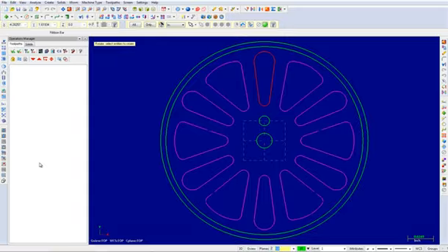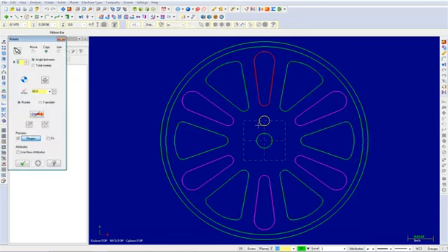Your part will appear as shown up to this point. Next, pick the following arc as shown. Press Enter. When the Rotate dialog box appears, ensure that Copy is enabled and that the number of copies is set to 5. Also, ensure that Angle Between is enabled with a degree value of 60.